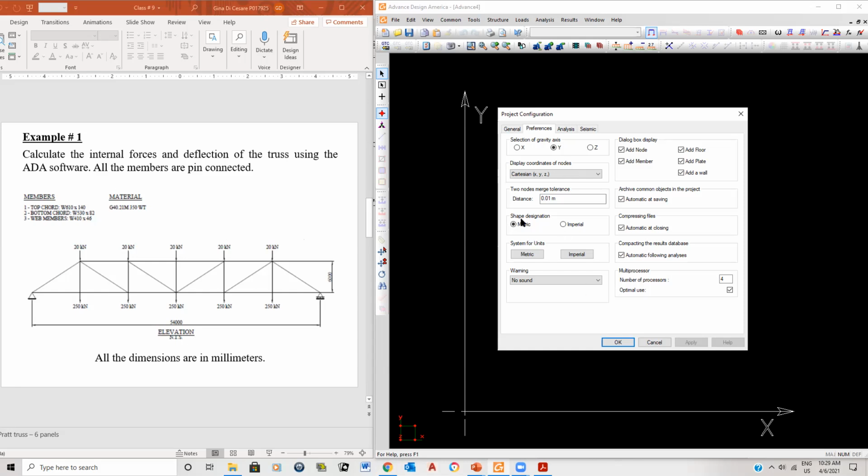You can have imperial geometry and metric shapes, or metric shapes and imperial geometry. So you can pick and choose here. And if it's metric, of course, make sure that these are both on. And like I said, if you see the blue around this one, that's what you're working on. And these dialog boxes are something you should remove by default. They're always checked on, so this way they won't pop up in your face every time you add a member